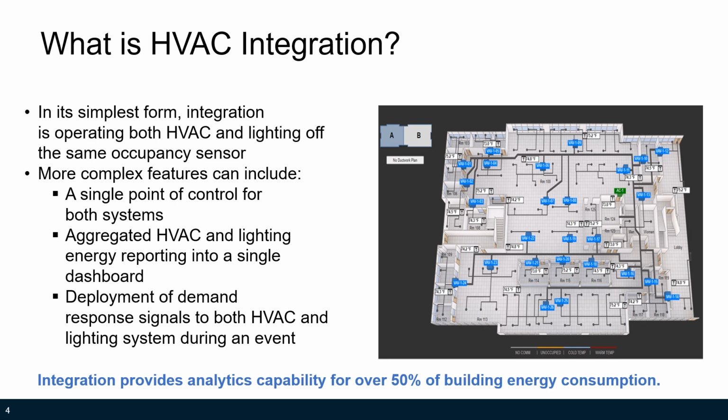For example, in the case of a demand response situation, light levels can be dimmed along with raising HVAC temperature set points for cooling. This can minimize the discomfort that can occur when only HVAC is considered, with really very little effect on lighting performance.